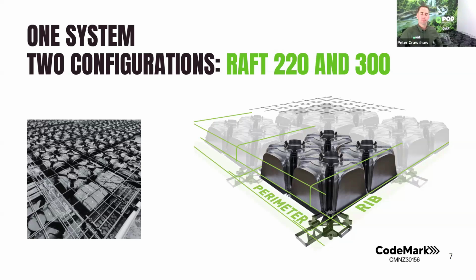We have done a few with stirrups, and that's purely because the client wanted a polished floor and did not want fibres shown in it, so they had to do stirrups. But boy, oh boy, the labour with stirrups is not very friendly to the contractors. So fibre is the way to go there if you can.